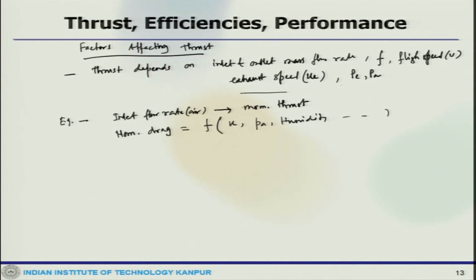Similarly, the outlet gas mass flow rate is dependent on how much fuel is added, air bleed, and water injections. Then the pressure thrust term also depends on turbine inlet temperature, flight altitude, and nozzle outlet area, and the momentum thrust also depends on jet velocity. So, these are multiple factors which affect thrust. Some of the important factors are, let us say, the jet nozzle.